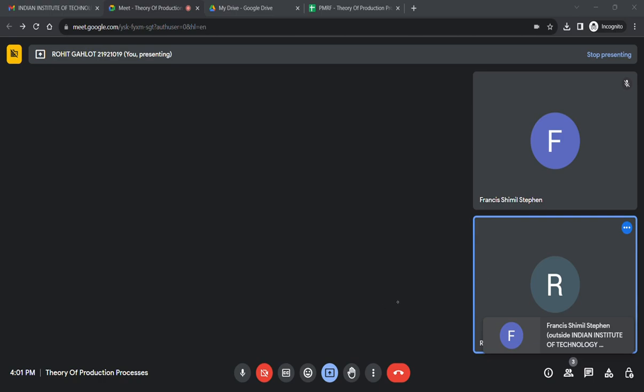Generally the width is written as pi times d mean. Why it is taken this way, you can search on the net for the derivation. But generally it is taken as pi times d mean, or you can understand this by your basic imagination. So pi times d mean will be 30 times (30 plus 20) by 2. By calculating, it will come as around 25 pi. Then you can directly calculate the shape factor.